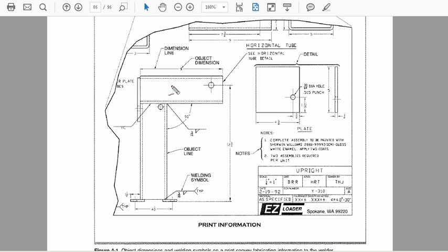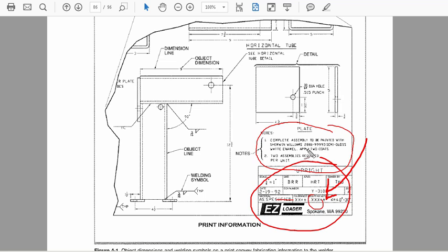First of all, we had a drawing that actually included an enlarged view of a part, or a breakout view. And we're used to our normal title block. Let's see if I can change this a little bit. There we go. We got our typical title block. We have our standard information associated with it: material, tolerances, who did it, that kind of thing. We even have some specific notes. These are actually the instructions associated with the print. We would refer to these as local notes because they don't deal with anything more than what's on this page.